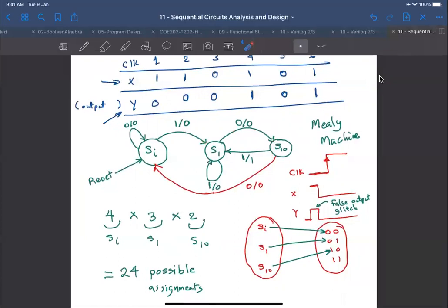Once you finish deriving the detection path, you start with the other alternatives. So here, when you receive a 1, you go here. But what about when you receive a 0? Here, when you receive a 0, you go here. What about when you receive a 1? And here, when you receive a 1, you go here. What about when you receive a 0? So think where to go next, keeping in your mind that overlapping is allowed. So which state do we go next? And what do you think the previous inputs get us to, which state?